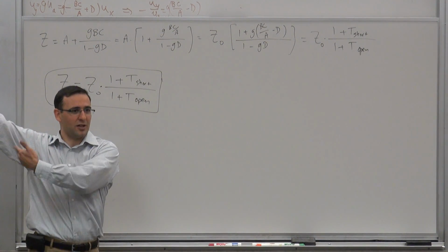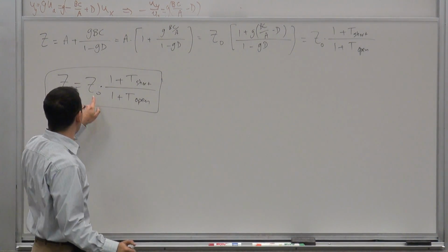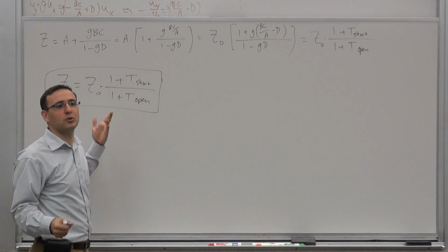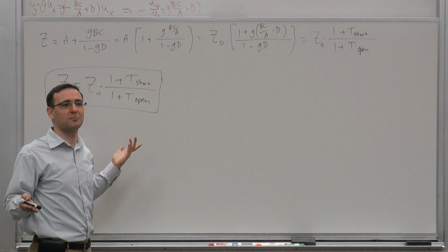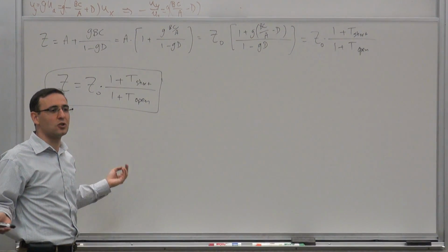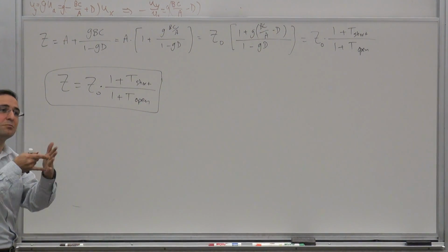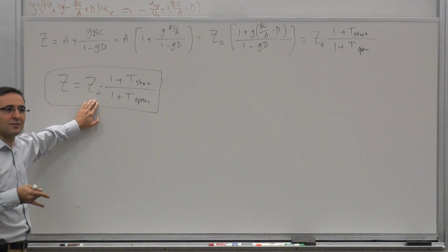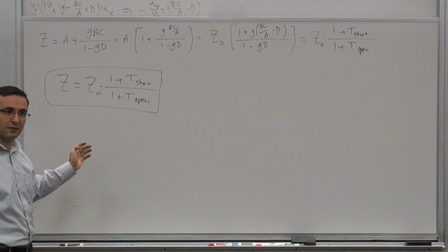If I choose some irrelevant source, what happens is that Z naught becomes Z, right? So then it doesn't help you in solving any problems. It just basically is as difficult as it used to be. So you want to pick a source that makes the calculation of that impedance as simple as possible. That's Z naught. Basically eliminates the effect of feedback, ideally.